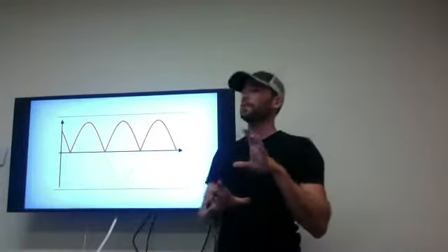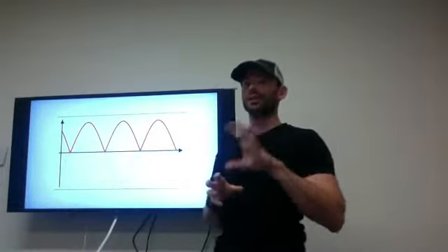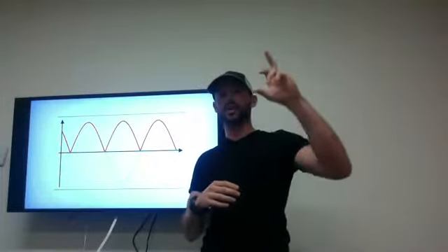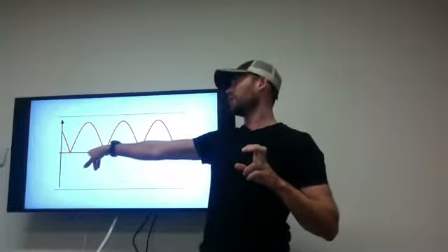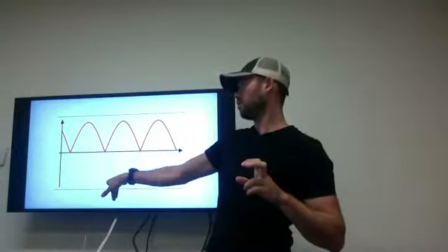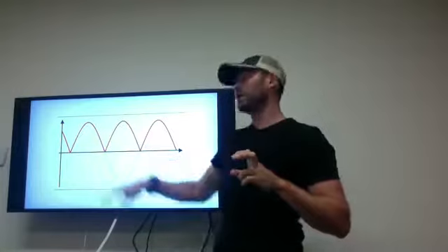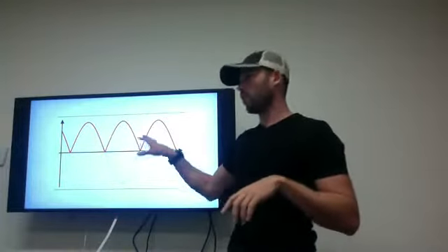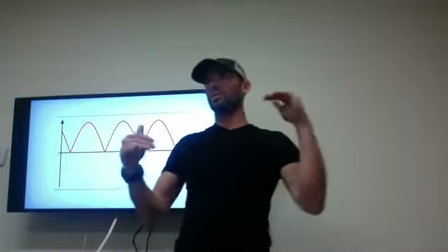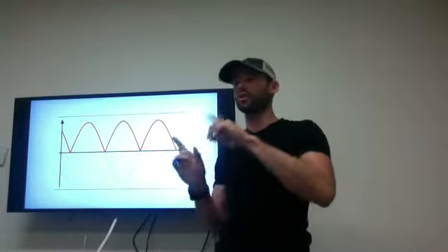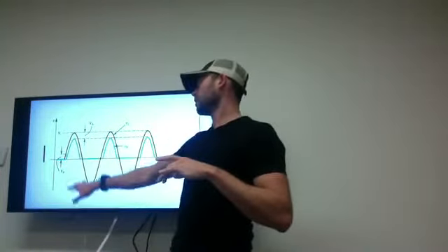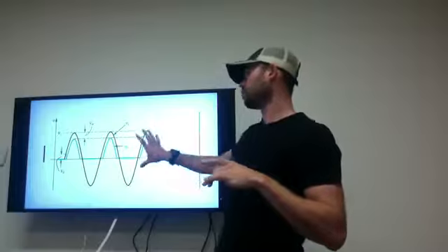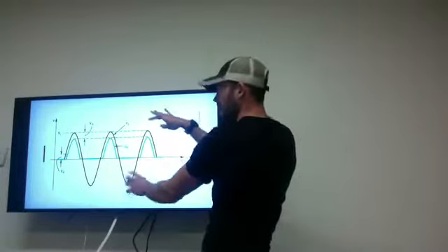Now, the bridge rectifier takes that sine wave, which we can either scale up or shift, and it creates the rectified signal, the magnitude of the sine wave. This signal is what is going to be pushed through the RC circuit in order to create the DC voltage. Before we get there, the sine wave has this full magnitude, so this is the ideal input.